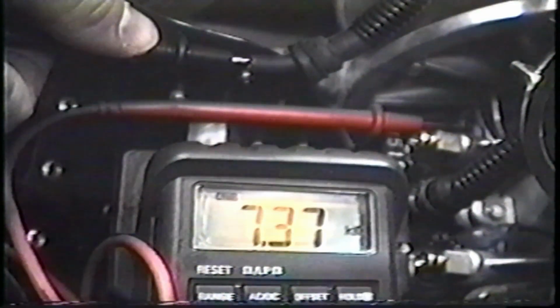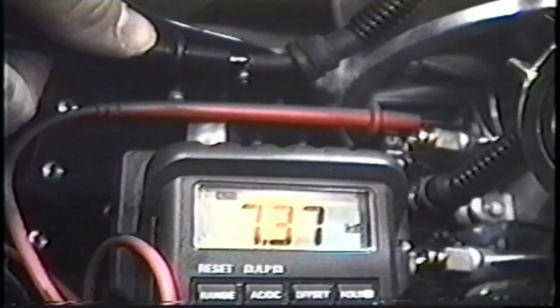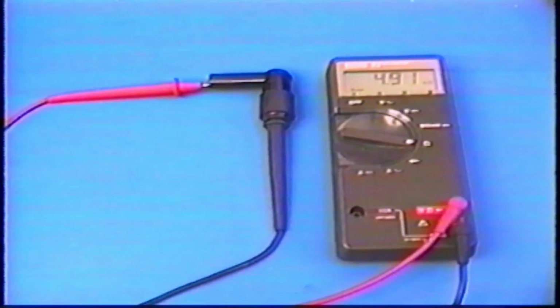If the AC generator coils are within specs, check the ignition coils. On a multi-cylinder engine, each coil should be tested individually. The resistance of the secondary winding should be checked with the spark plug cap removed. Then, test the plug cap separately.